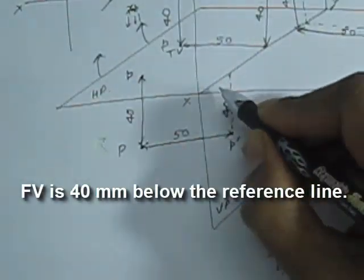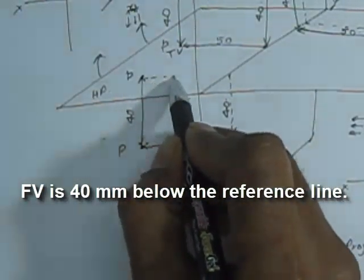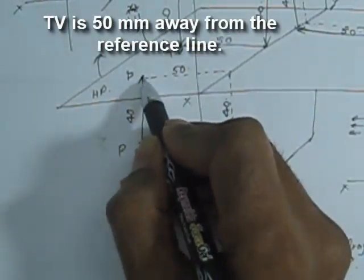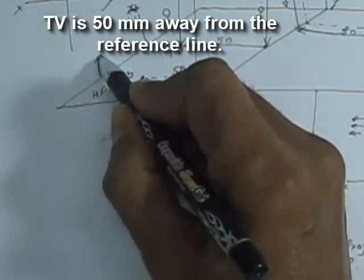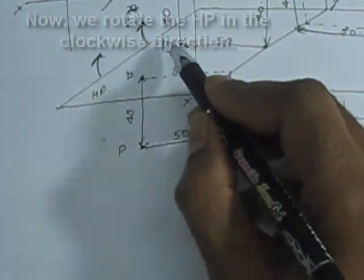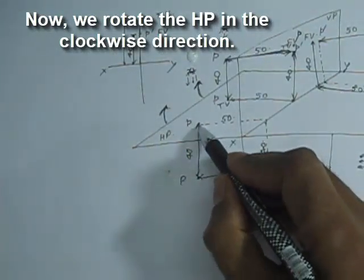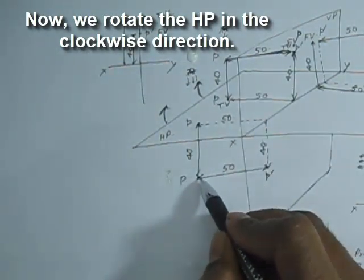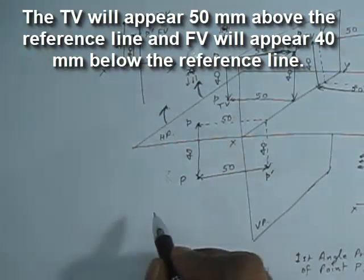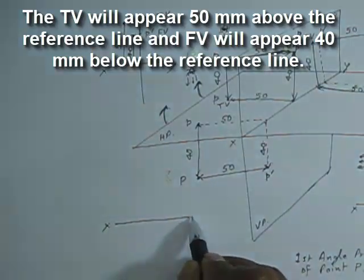So the front view is at 40 mm from the reference line, below the reference line, and the top view will be at a distance of 50 mm from the reference line. Now the horizontal plane will be rotated in clockwise direction such that the top view will go above the reference line when we make it into a 2D. The front view remains below the reference line. So let's see how we can draw it.